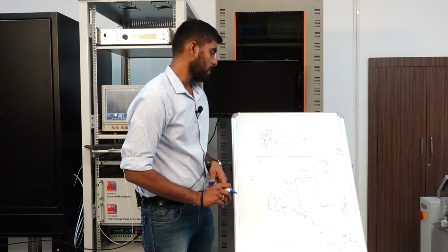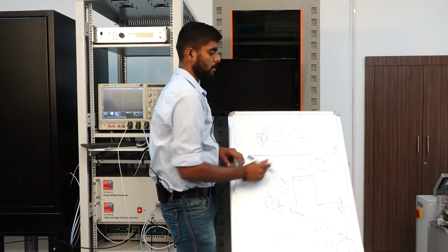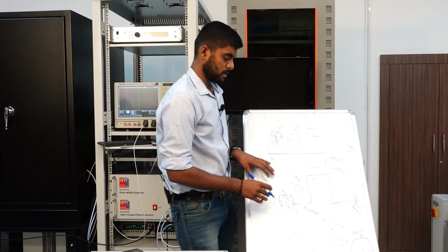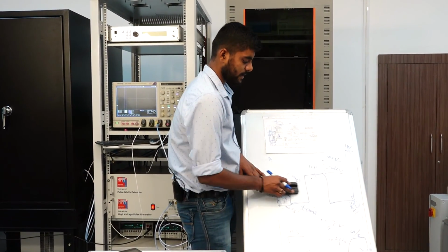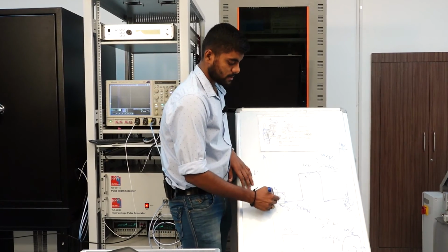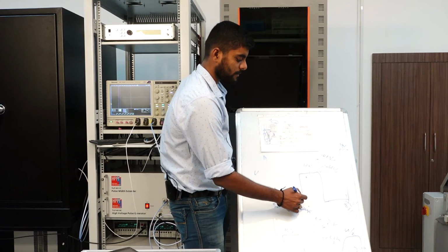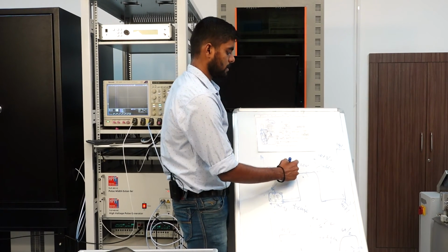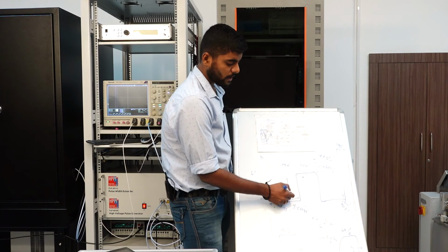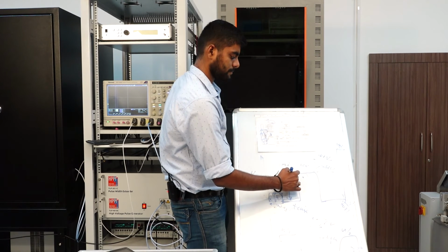I was also, if you remember, talking about the SMU and applying a low voltage bias in the off time. Now that I'm discussing this, I'll discuss it as well. When you have applied a voltage pulse to the device through a TLP generator, this off time is a very high off time. And why waste this off time, right? So what you do is you apply a very low voltage DC bias to the device under test.